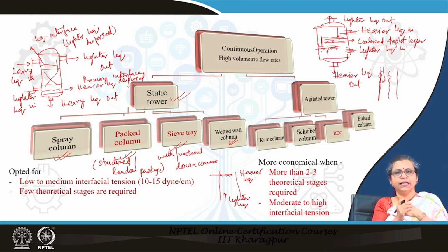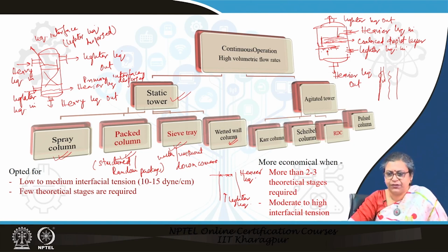Now, for such a case, if we can give some sort of motion or agitation or stirring to the liquid mixture, quite naturally we find that the number of theoretical stages will definitely come down, and it will be easy for us to disperse and get the mass transfer, and along with that to get the required separation that we require. So, quite often we find that in industries, instead of static towers, we go for agitated towers,